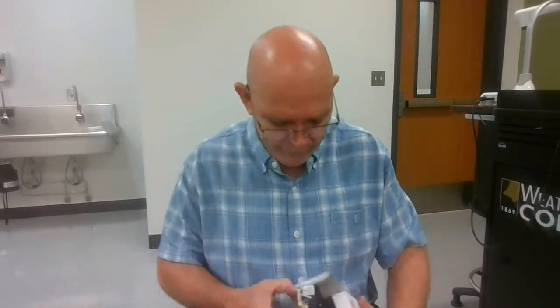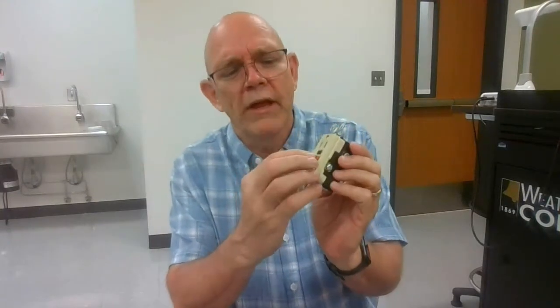Another thing we have to protect against is, say you have an appliance and you're in the kitchen or somewhere and the surface gets wet and the cord has a little cut in the insulation, and so some of the electricity is being conducted into the water. All right, if you stick your hand in the water, then guess what? You're going to be electrocuted. So any outlet that is around water is going to have what we call a GFCI, ground fault current interrupter. Sometimes they have red and black buttons.